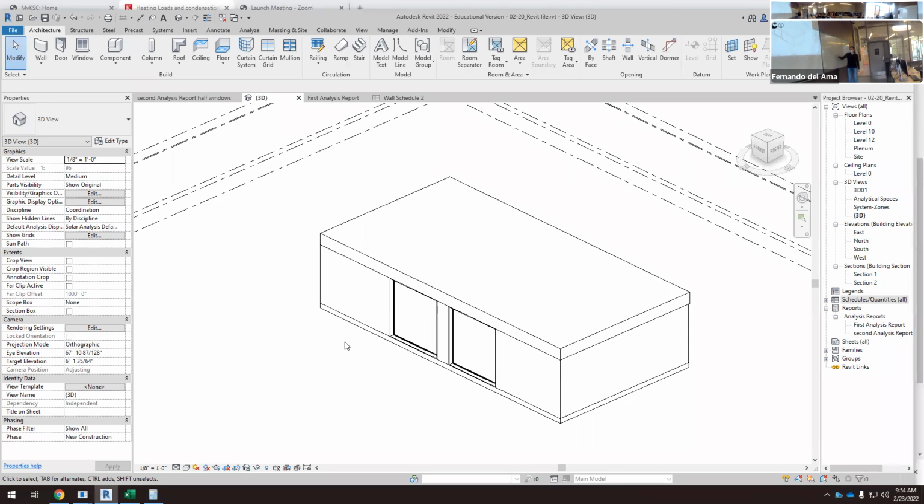And second, because the floor temperature is not as low as the outdoor air temperature. Okay, so sometimes we don't even have insulation in the floor. I don't recommend that. So I recommend always this value for the floor, because some of the heat we are losing through the floor, but we lose much more heat through the roof or through the windows than through the floor.